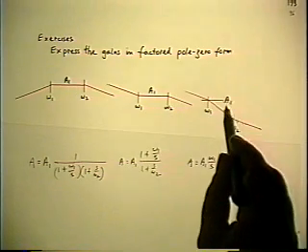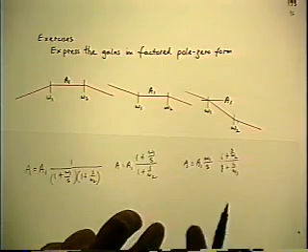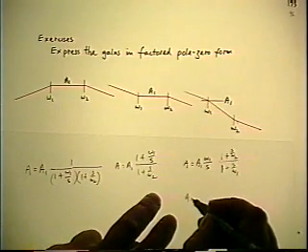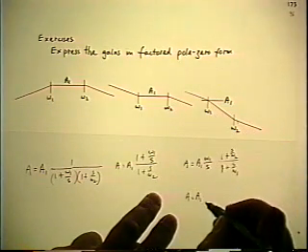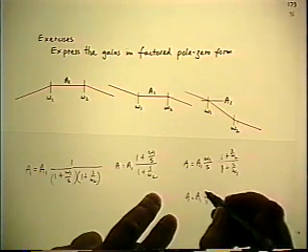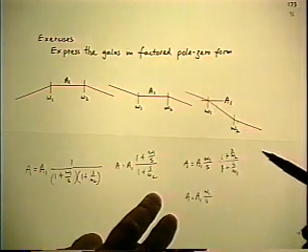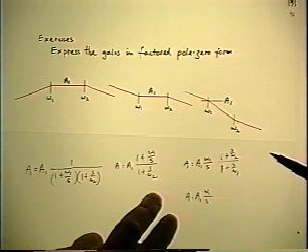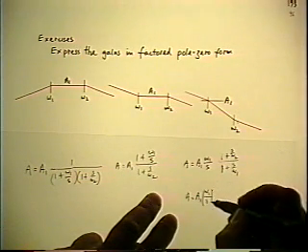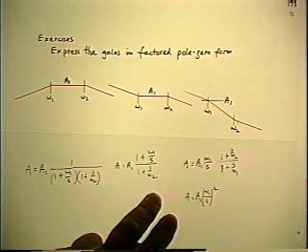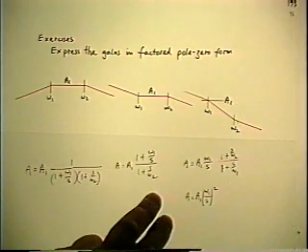We could have identified the A1 originally on the middle slope, in which case the first thing you write is A equals A1 at the frequency omega 1, so S will be in the denominator and omega 1 will be in the numerator. But this time, if we identify it with the middle slope, it's a double slope, minus 40 dB per decade, which means you have to square that term. Remember, it's double log scales.